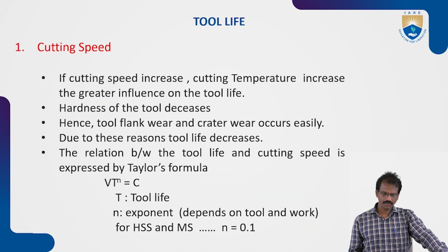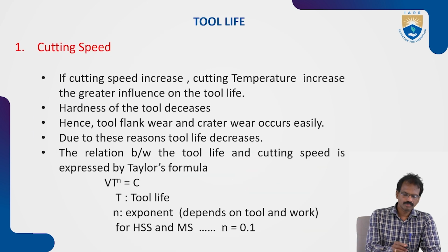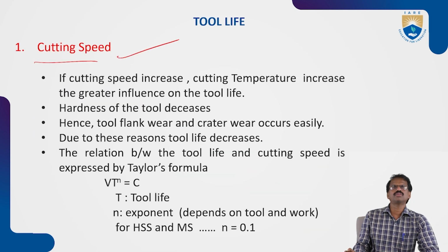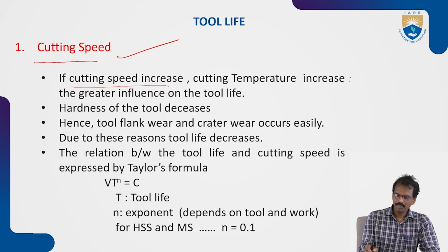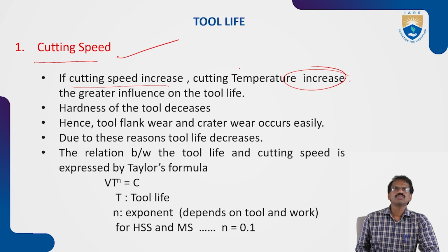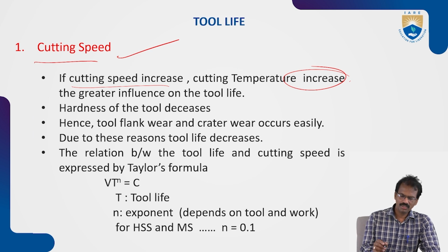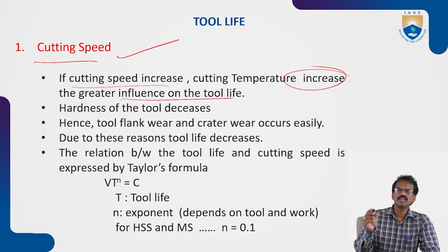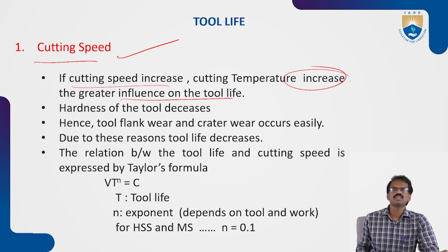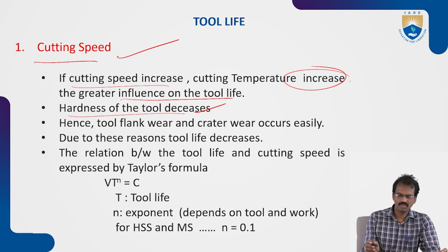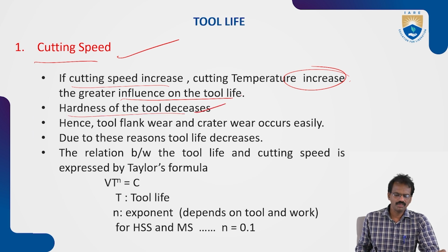We'll see first of all the cutting speed. This is a very important parameter. As the cutting speed increases, the cutting temperature increases. The greater the temperature, the more it influences the cutting tool life, because if the temperature increases, automatically the hardness of the tool decreases.